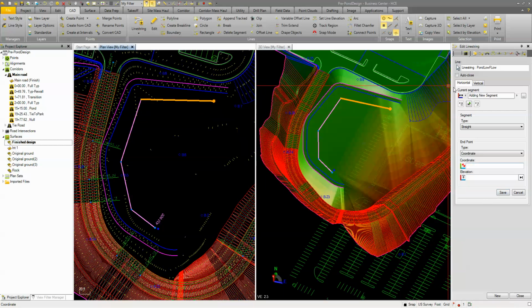Now at the top, I'm going to switch over to vertical, and I know that I need a 0.5% slope from this point up to here. So my incoming slope to this location at the end is going to be a positive 0.5%. So I'm just going to come in and say 0.5 and save. That determines that the top elevation is 439.854, so basically 439.85. So at a 0.5%, that's the elevation we needed up at that point there.